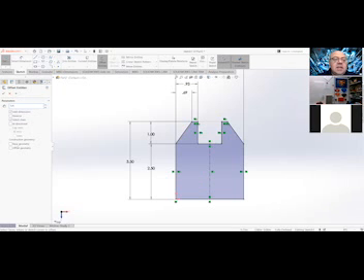Okay, now if we look at our options below that, it'll add the smart dimension for you, so you don't have to come back and do that. So we put in the distance and we'll let it add the dimension. I always add the dimension so I can change it later if I need to. If you don't, then you have to add it and it's just more work. And we don't want to do more work. We want to do it as simply and easily as we can. So 5/8 is where we're at.